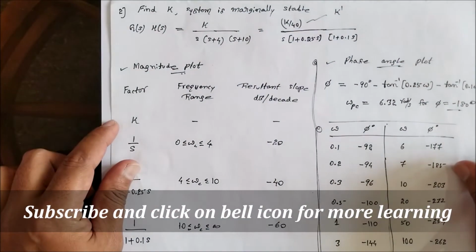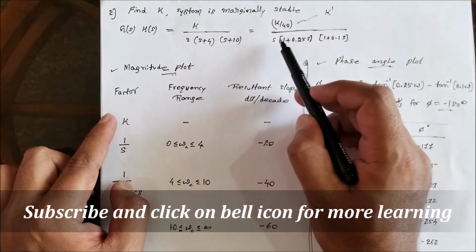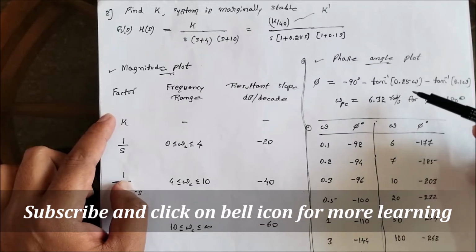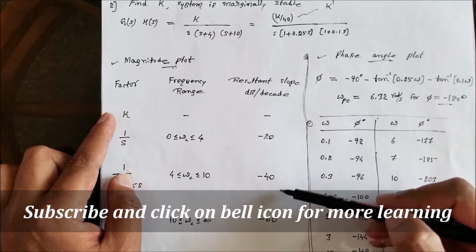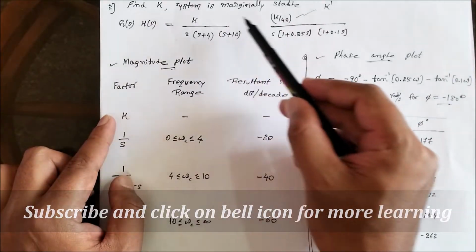Now moving ahead to step number 4 to plot the Bode attenuation curve, we have just determined the magnitude plot, that is the resultant slope table, as well as the phase angle table. The maximum resultant slope I require is minus 60 decibels per decade, and we want to find the value of k for marginal stability.